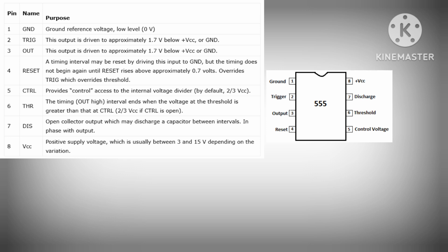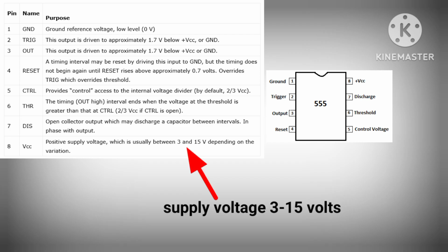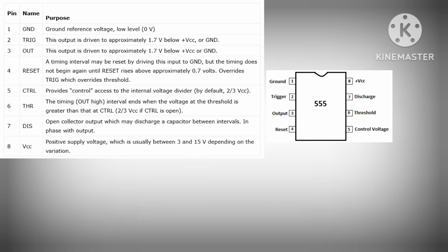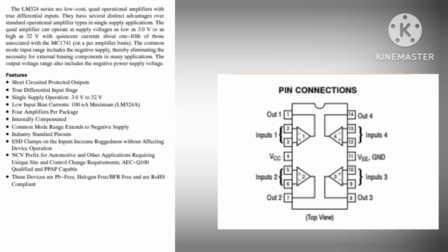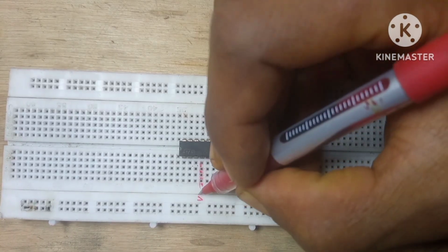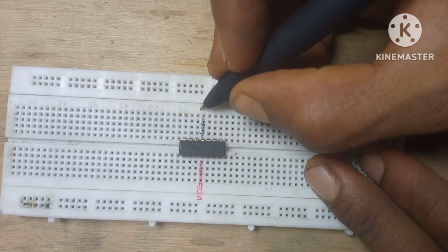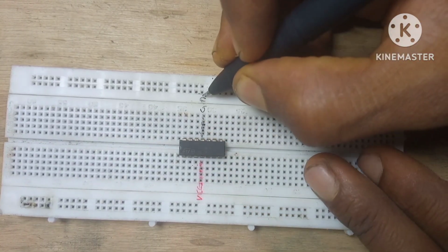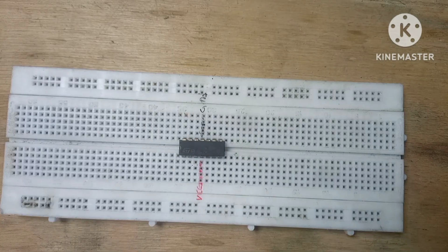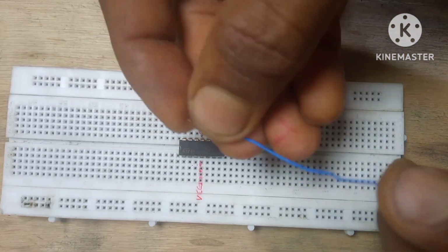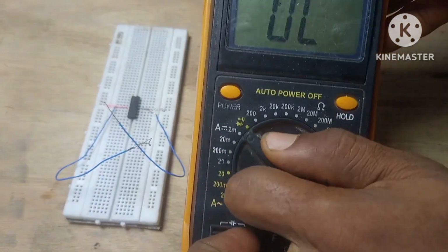On the datasheet of the IC, look for the supply voltage of the IC and its current. If it's not included, you can start with a low voltage supply like 3 to 5 volts and watch the current draw with a multimeter. Start by connecting the negative and positive wires from a DC power source to the IC negative and positive pins. Remember to start with a low voltage, or you can add in a resistor to the negative or positive pins of the IC to limit the current.